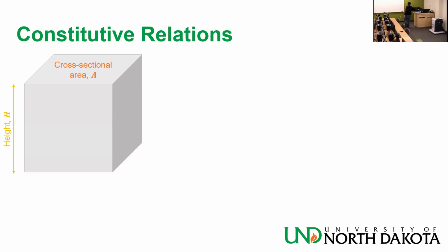Or what we use is linearly elastic fracture mechanics, which is based on linear elasticity with some modifications to account for the fracture. But constitutive relationships always think about stress and deformation, or stress-strain. Always think of that when you see the word constitutive. And constitutive model, yeah, linear elasticity, etc.